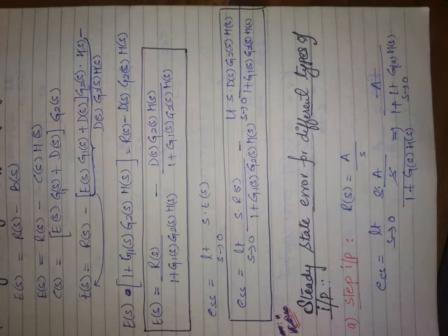We are writing it as R minus B. We are not writing error as R minus C directly. R minus B का मतलब क्या? B will indicate output if and only if H is a sensor or transducer. If it is not a sensor or transducer, then H should be unity, then only B will be equal to C. This is understood? Yes or no?